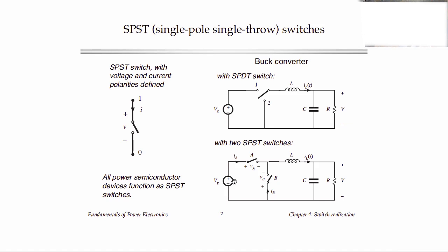For this particular example of the buck converter, if you turn both switches on at once, you probably destroy your switches because you short out the power source and you can get a very large current flowing around this loop that can destroy the devices or at least cause a lot of power loss. So we have to go to some lengths in our drive circuit to make sure that that never happens, even for a few nanoseconds.